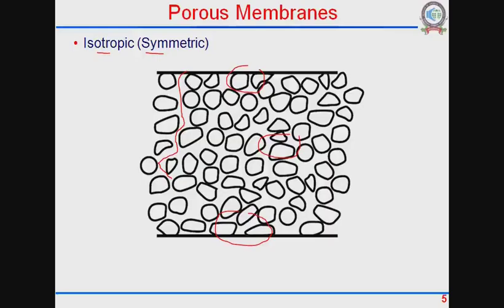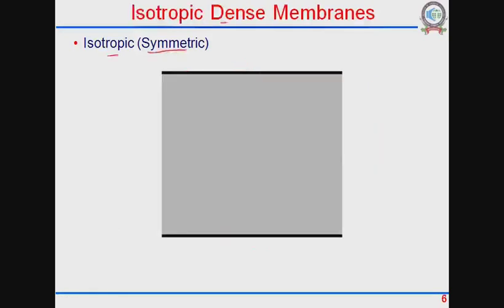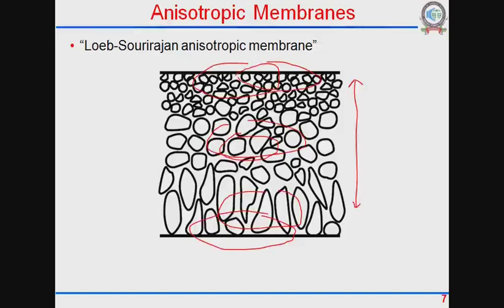That's because the resistance offered by this cloth or by this membrane was proportional to the thickness of that membrane. So now imagine that we are trying to filter out small particles. Therefore we need very small pore sizes, and then if we have a membrane which is thick, then we will require a very large pressure drop, or the filtration flux would be very small. So the option to get high filtration rate is to have a very thin membrane, right?